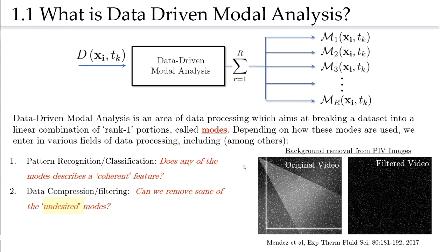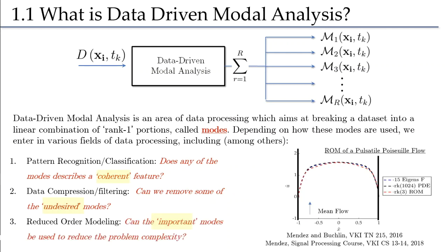Or you might wonder if some of the important modes can be used as a basis for reducing the complexity of a problem. In this case, you enter the realm of reduced order modeling. Here the goal is to combine data-driven modal analysis with numerical schemes. By projecting a problem onto the basis spanned by a few of the leading modes, we can convert partial differential equations into a very reduced set of ordinary differential equations and then significantly reduce the computational cost.